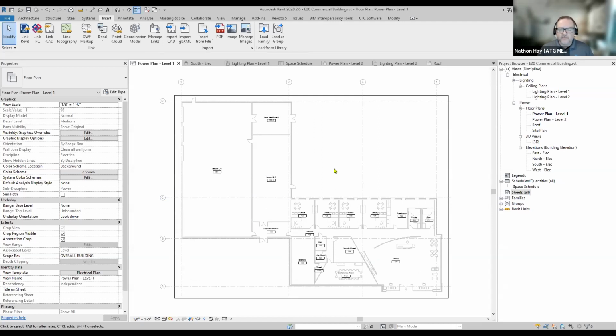The next things we're going to talk about when I do another webinar, probably in a month or so, and there'll be a white paper on it, is designing the distribution system. So I'm going to walk you through out of the box with the stuff Revit doesn't come with. I'm going to show you how to get your power panels in there, how to put some receptacles in, how to put in some data drops, how to circuit that stuff and get it to show up on a panel schedule and get it to do your load classification calculations correctly and give you a total amperage.